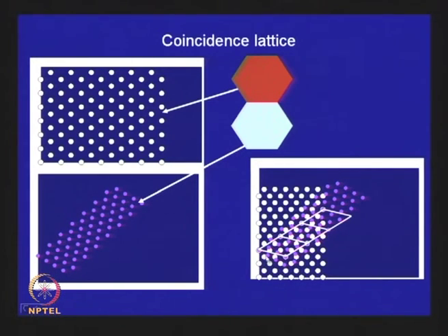coincident lattice site, and what you can find out, this coincident lattice distance is significantly larger than this atomic distance. Like in this particular case, you see that here this is one atomic distance. So, here it covers the distance, this distance is 1, 2, 3. So, that means this coincident lattice dimension is 3 times the main lattice dimensions, and by this it is possible to relate and find out the surface energy or energy of the grain boundary, and this energy has a relationship between this angular rotation between the neighboring grains, and that is how the grain boundary energies are classified.